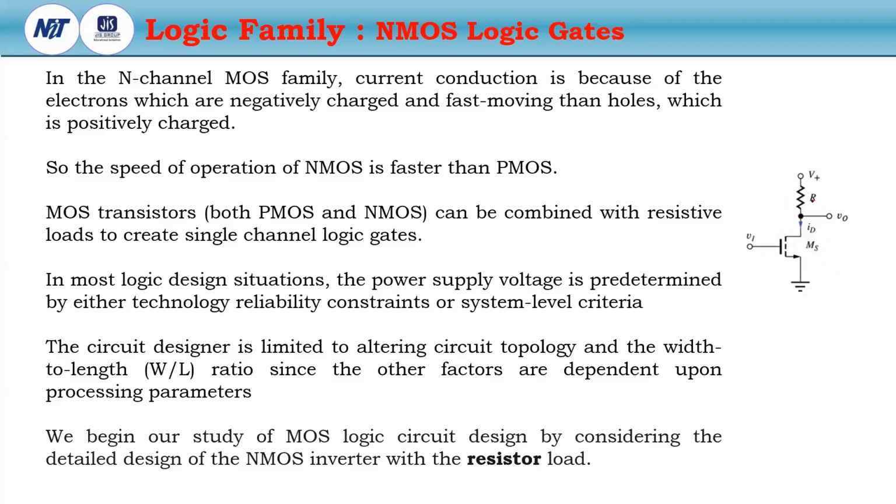Okay. So now first, when we use the NMOS, then the resistance was used as a load. But for the fabrication issues, the area of the resistance is very high, and it is also noise prone and non-linear.